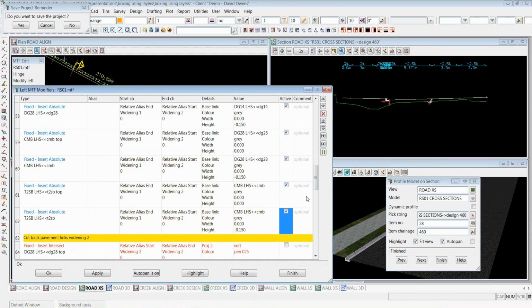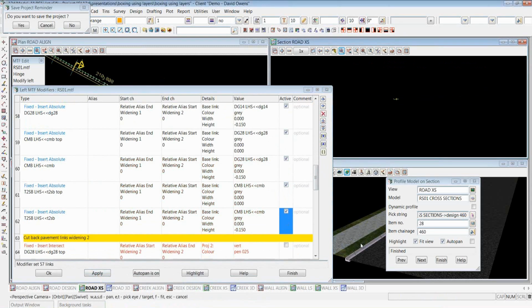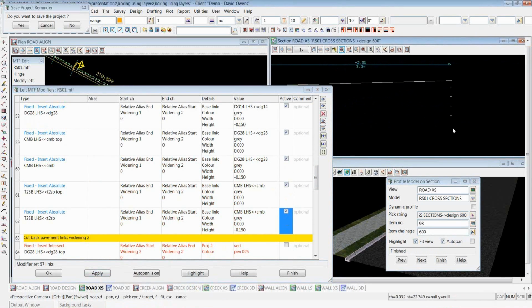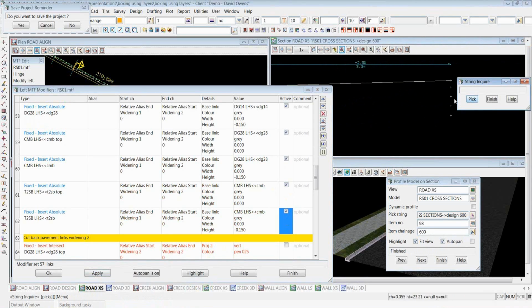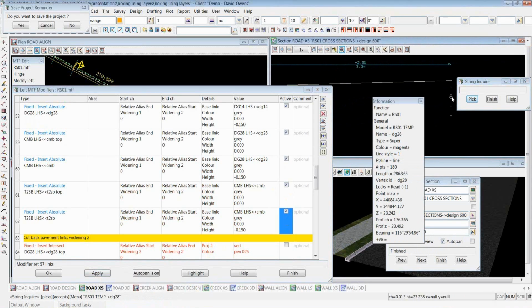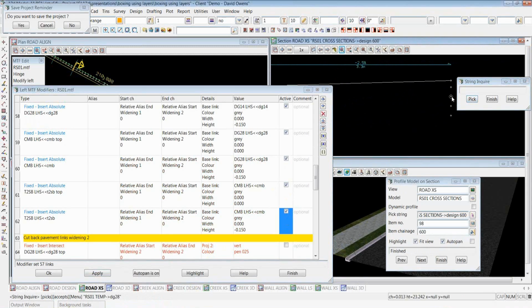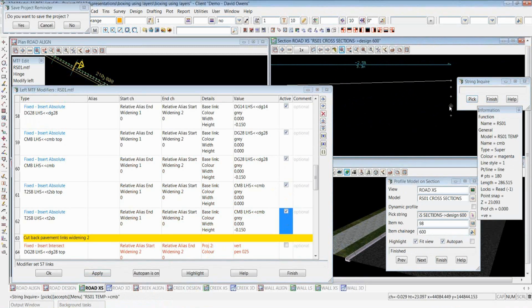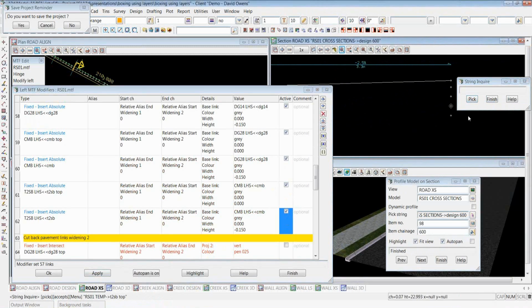And that is the whole thrust of this thing. I'm trying to find nice, simple, easy to use commands that construct these points wherever I need them. Okay. So if I go now and have a look at, say, change up 600 or something, where I'm building some full pavement for all my construction points. So some of these are duplicates. Okay. The DG28 is also the top of my cement modified. The cement modified is also the top of my type 2, etc., etc.